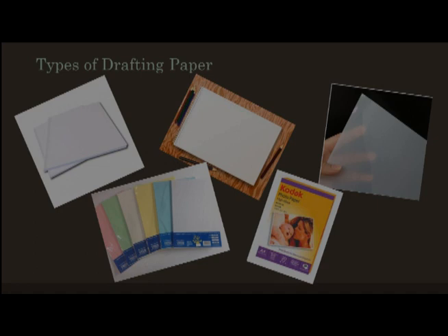It is still used with drafting plotters, and it is available in roll form and in cut sheets. Mylar has a shiny side and a matte side, and you draw on the matte side. So we are putting our drawings on the matte side.